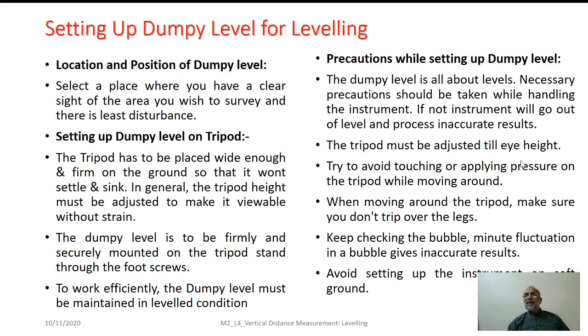One must see that the tripod is adjusted to the appropriate height. One must not simply touch or apply pressure on the equipment while taking the readings. It is also good practice to keep on checking the position of the bubble after every reading.